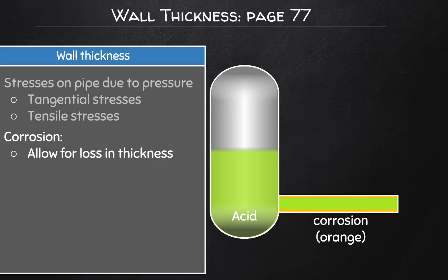So you must consider the concentrations and whether there are any even trace elements or dissolved salts present in the solution that you're pumping around, because these can cause corrosion, believe it or not. So chemical processes will always surprise you with their non-idealistic existences, and so don't treat them ideally. Always treat them in a realistic way and assume the worst rather than the best.